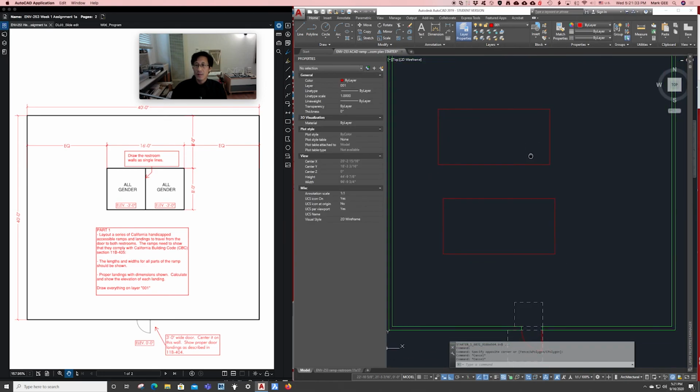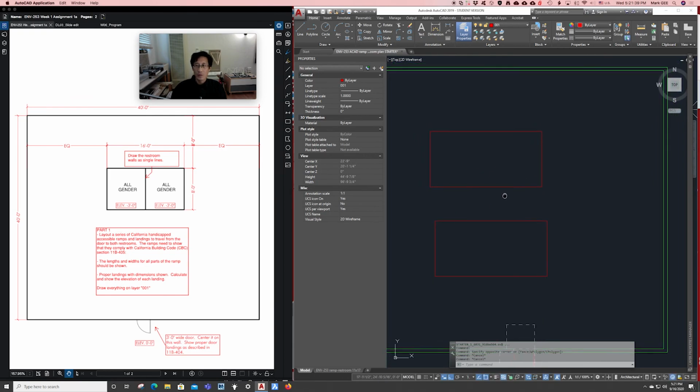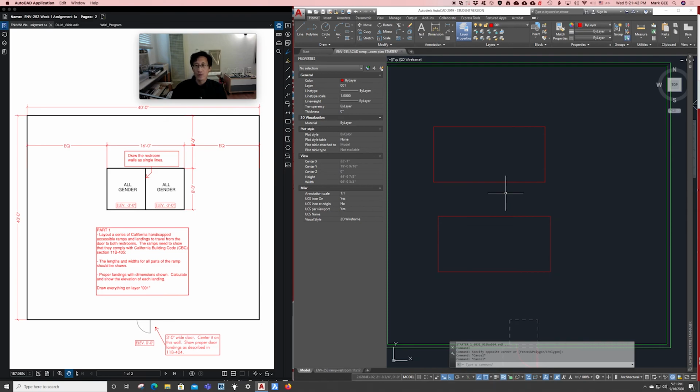One more way of drawing this, the rectangle command. Here, I'm going to explain how to enter relative coordinates. Just like when we drew the first line, or any of these lines from point to point, we moved the mouse and told AutoCAD we want to go that distance from the first point. Relative coordinates in AutoCAD are a similar thing, but you need to give both X and Y from that first point. When we draw a rectangle object, we'll click one corner and then draw the opposite corner.